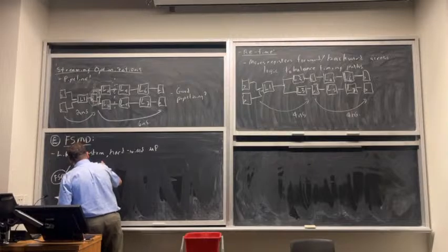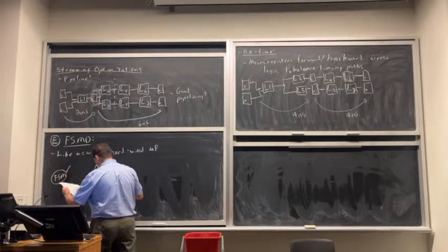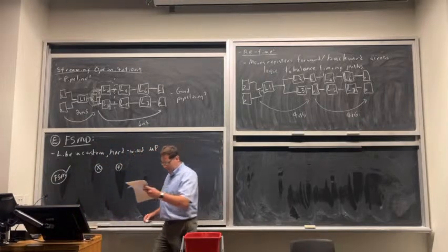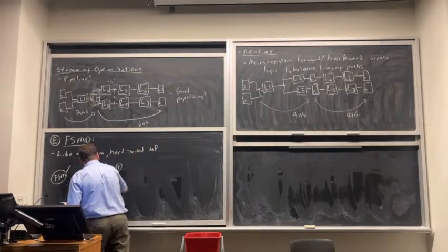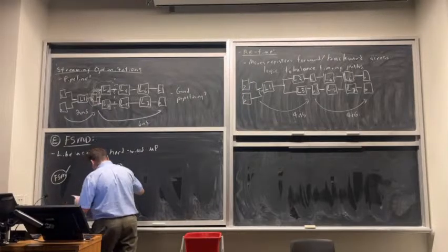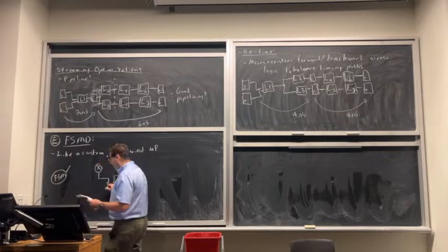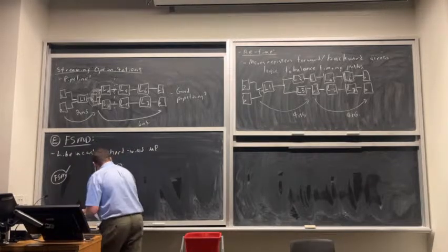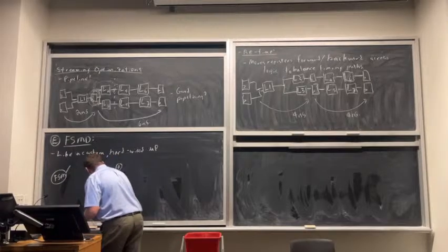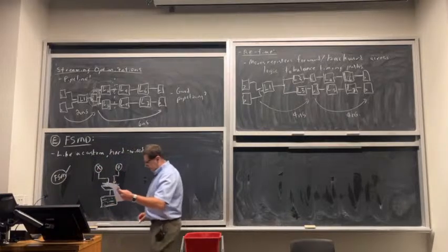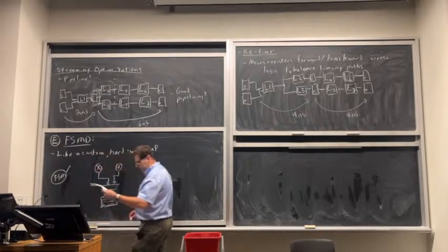Let's say I've got some computation I want to do, like the quadratic equation that we looked at in the first lecture. I needed a multiplier and an adder, because I had multiplies and adds. I need to select what I'm doing, and I need to be able to store my outputs, so I've got some bank of registers, a register bank.